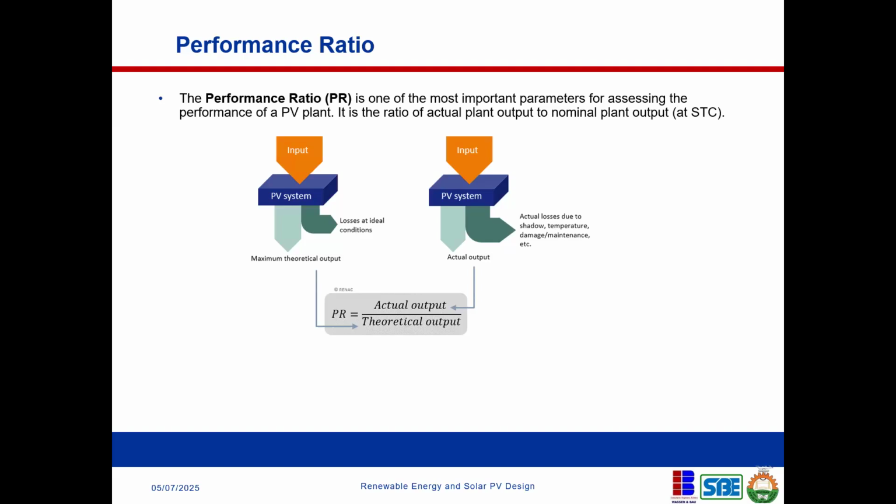When you install that solar panel, you might not get 300 watts. The difference between that 300 watts and what you actually got over a period of time is what we know as performance ratio. Some PV systems might be performing at a 65% performance ratio. What that simply means is that they are performing at 65% of their standard test condition rating.